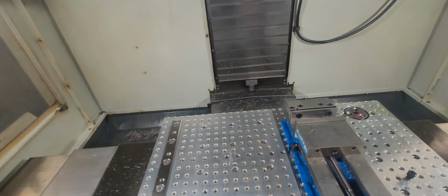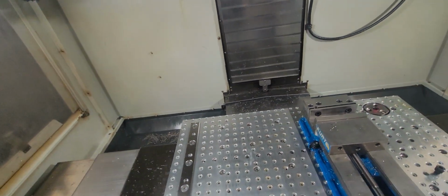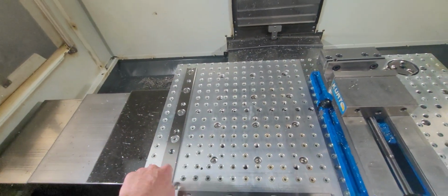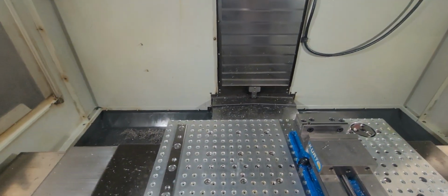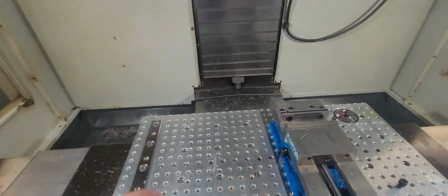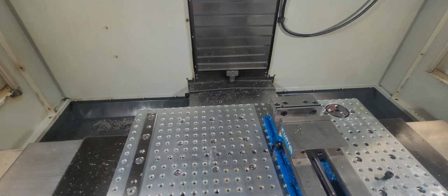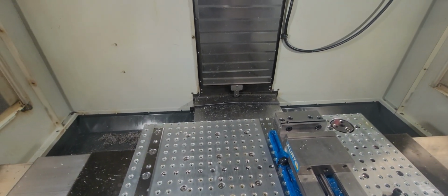This section here is for backside chamfer. So this corner, this origin here, is always a known position, and I've got that in a G56. So anytime I've got a back chamfer, put it on here, clamps against the side, boom, I can chamfer without even setting an X and a Y.